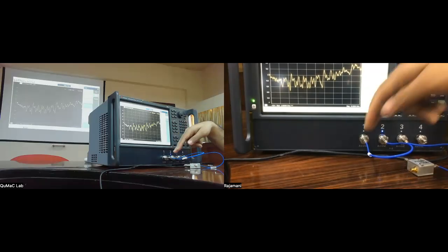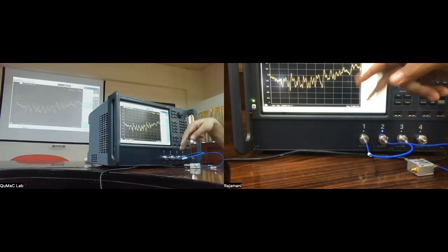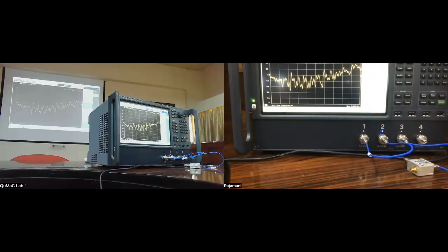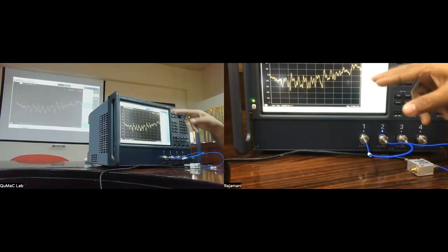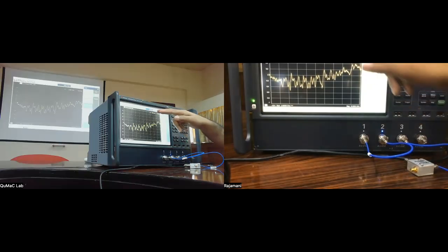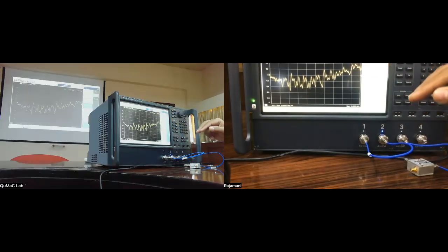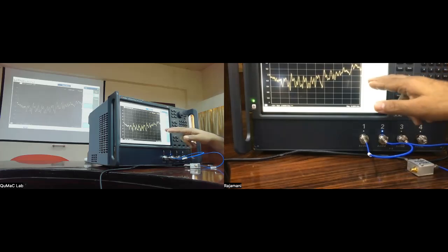So it's not as long as this expects, because the speed of light is slower in this medium. That really doesn't matter. What matters is the delta t you have dialed in, because delta t depends on velocity and distance. That's the number which really determines this. You can also enter them in other ways; I could have gone into this menu and entered it, provided I put the velocity factor here correctly.